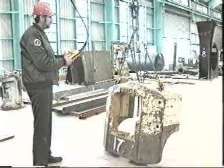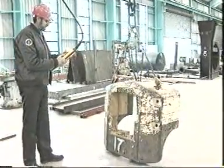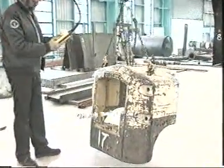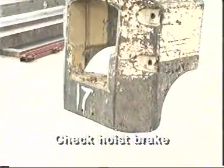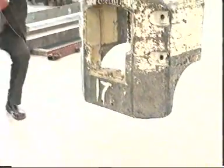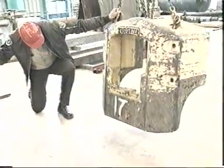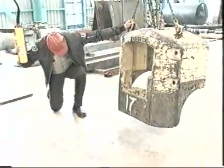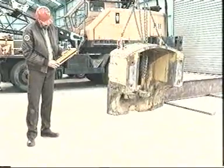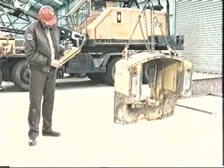As a final pre-operation check, you should conduct a trial lift to ensure that the electromagnetic or other hoist rope braking system is working correctly. Choose a near capacity load and raise it just off the ground. After checking for any brake slippage, raise the load up about 1 meter and recheck for slippage. Finally, lower the load till it's just off the ground, reapply the brake and check for movement.